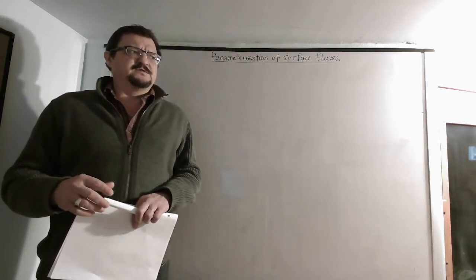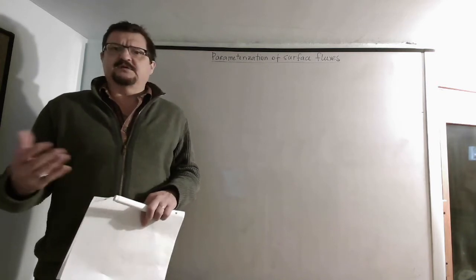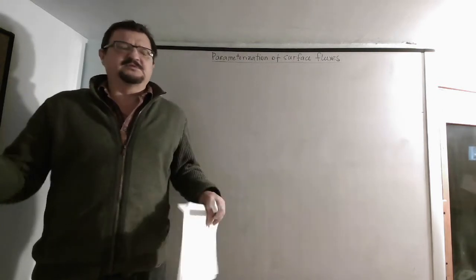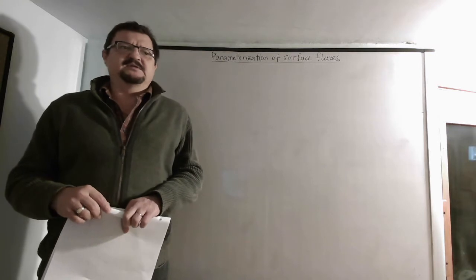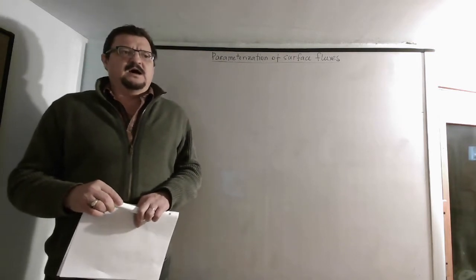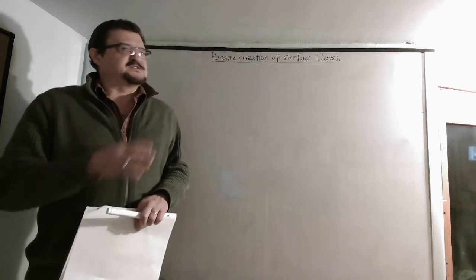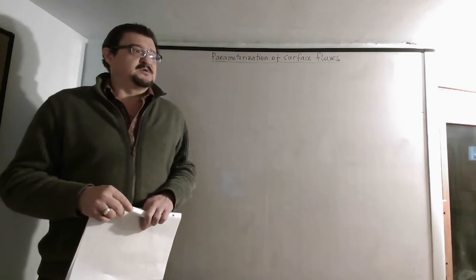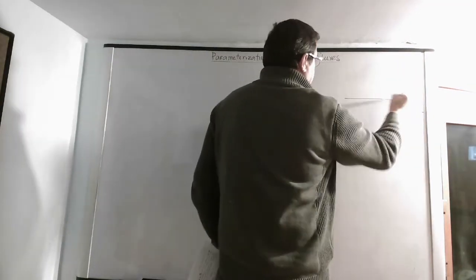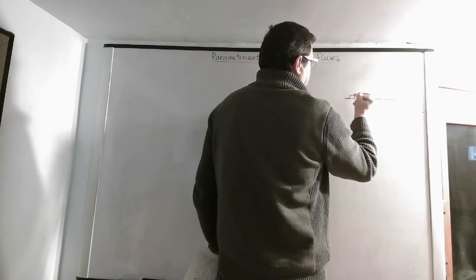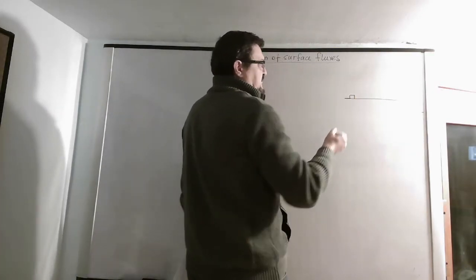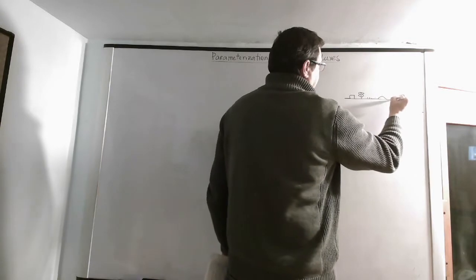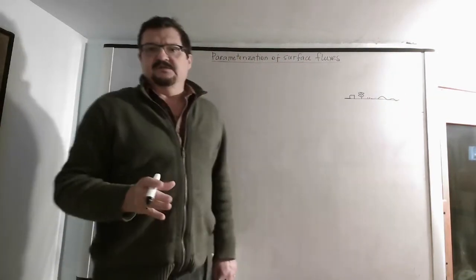And all our theory of the inertial subrange of turbulence, when we assume that turbulence is isotropic, so it's statistically the same in all directions, and dissipation only happens at very small scales and so on, and there is this cascade of turbulence from large eddies to small eddies, is not very valid right near the surface, because near the surface you actually have some obstacles, like in the case of the atmosphere, you can have houses, you can have trees, you have grass, you can have a water surface, and all those have very different effects on turbulence.